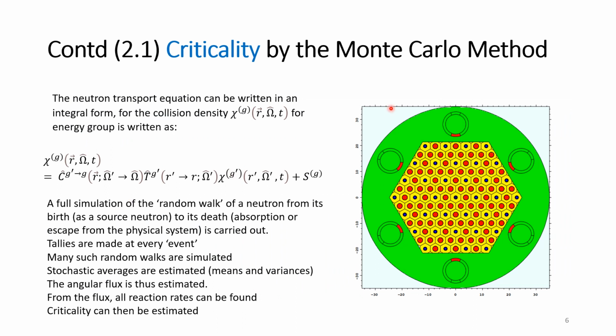Now, this shows you a plan view of a small micro nuclear heat pipe reactor. The green is the beryllium oxide reflector. The drums are rotatable absorber drums. The hexagonal monolithic core has red fuel elements, in this case uranium nitride, 70% enriched. It's a small reactor, with the blue being the heat pipes, which transfer heat out of the reactor, take it up to some Stirling engine or thermoelectric generator or any turbine system to convert thermal energy into mechanical into electrical energy.